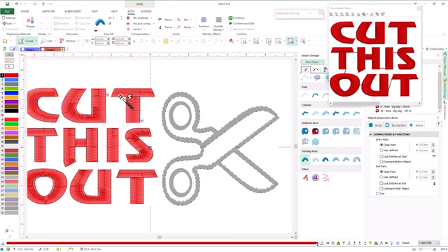Select the needle. Click to recognize all the contours and press Enter. The system creates the outline and adds the necessary cut lines and directions. Repeat for this object. And for this last one.